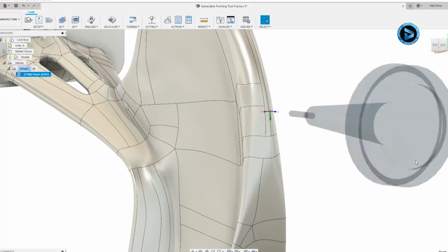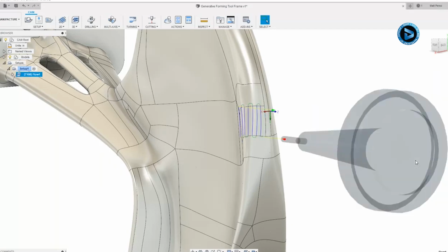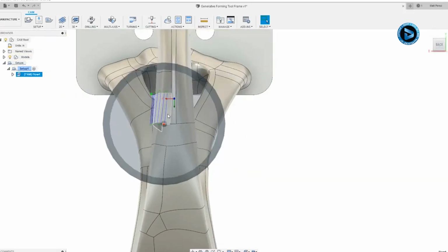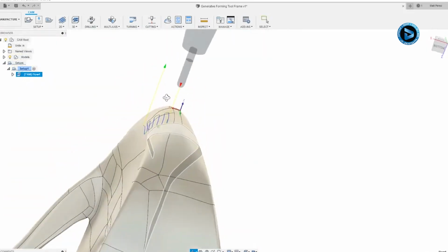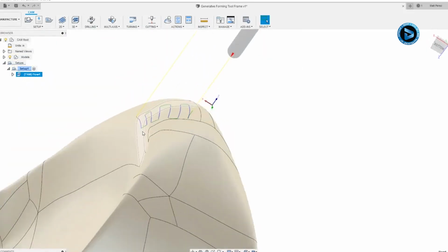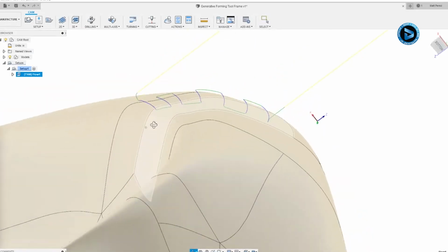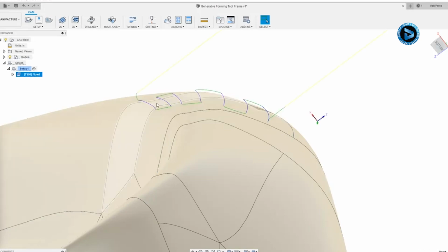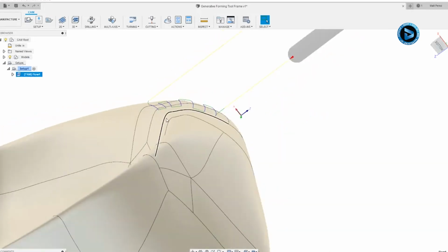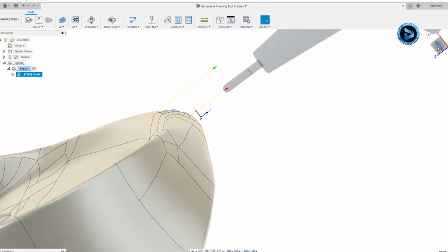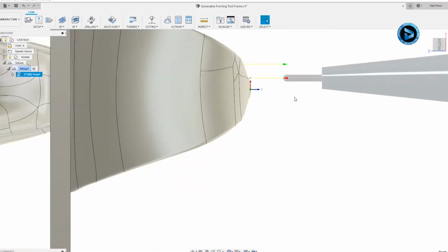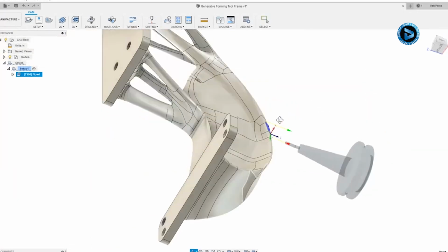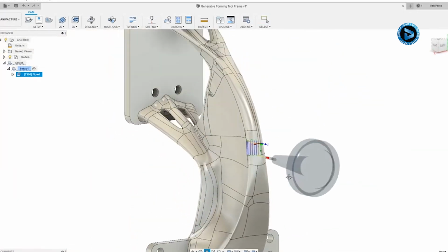When we're dealing with a multi-axis toolpath like this multi-axis flow, but we're using it in 3 axes, we need to ensure that the toolpaths that are created are not negating some of those settings. So you can see that even though this face wraps around the part, there's an area where the tool can't get to in a 3-axis operation. So this is exactly what we want to validate, just to ensure that the tool motion is respecting the 3-axis representation of the toolpath.